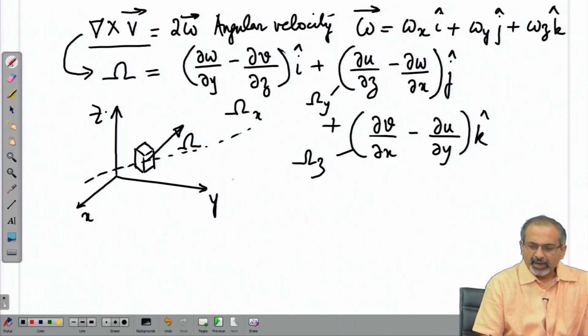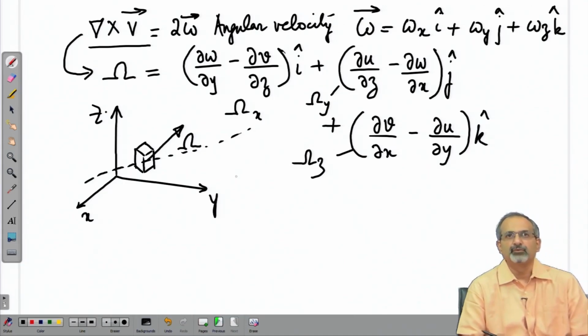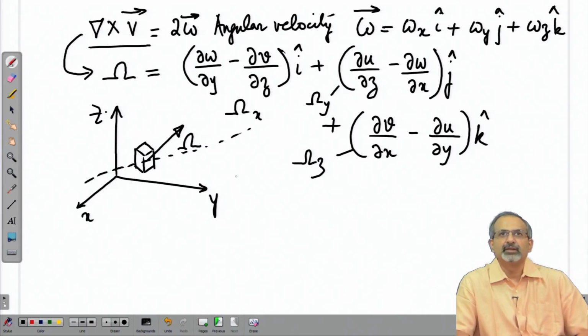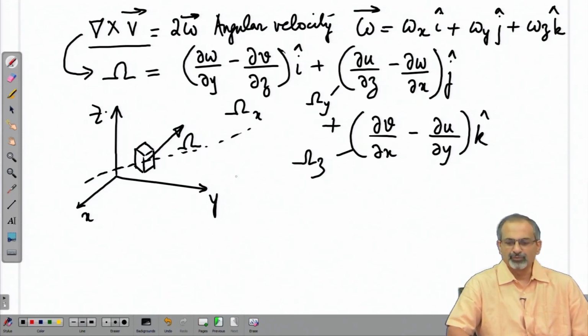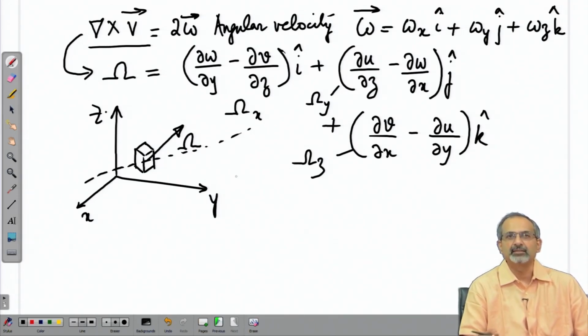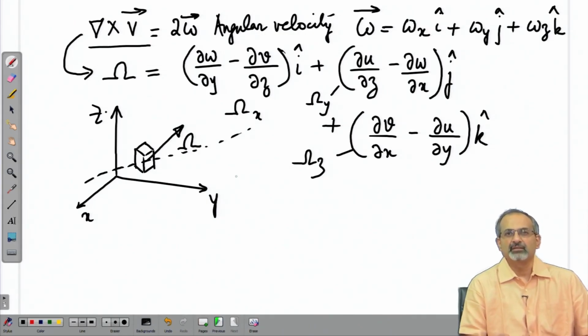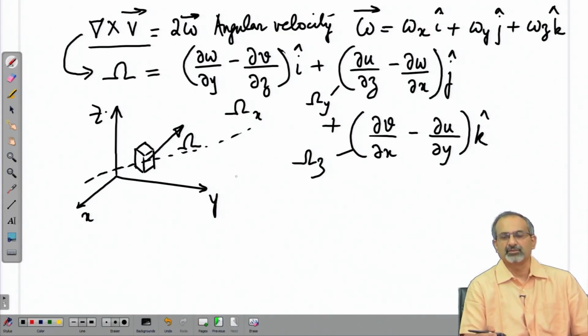Now, as we follow the fluid element, we move to different parts of the flow field, and in different parts the velocity vector has different components u, v, w. We are moving through regions where the velocity is changing continuously as a function of space, and if it is an unsteady flow field, additionally as a function of time.